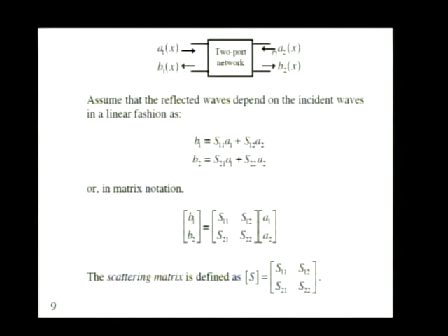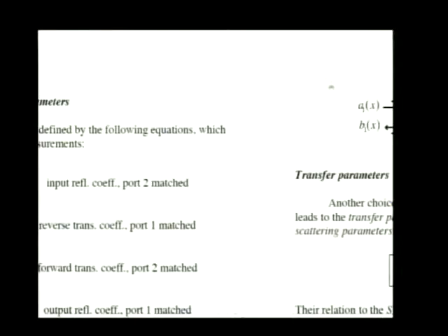That's how you measure the scattering parameters. They're not open circuit parameters. They're not short circuit parameters. They're match termination parameters. They're parameters that you measure using match terminations.